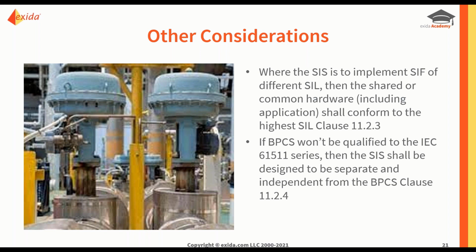So these are the things that have to be considered. And as I said, the problem with legacy systems is that these are already there. So we just have to make sure that, number one, we are following useful life, because that's usually what happens, is these things have been running for years and they're well beyond their useful life. That's a whole different can of worms, and there will be another webinar on that. And the other thing is, if it's not certified, then we've got to do some form of systematic justification. And that, according to 61511, is going to be doing a prior use justification.